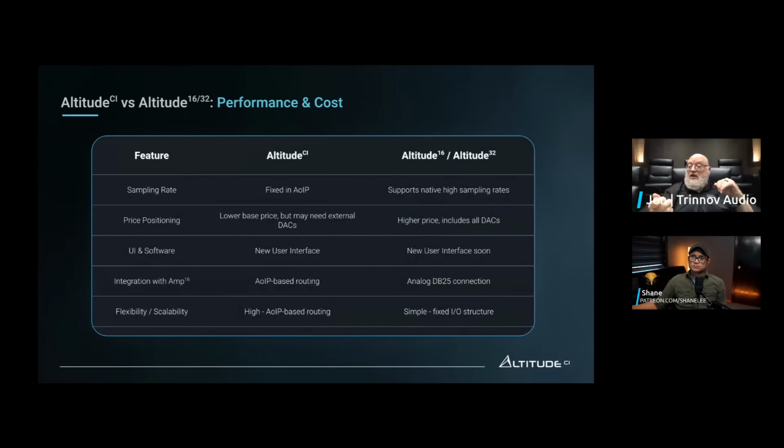And if you use the analog outputs or the AES/EBU digital, the conventional digital outputs of the CI, we will give you that 96 or 192 kilohertz result of all of our processing. But through audio over IP, it has to go down to the lowest common denominator that everything else on the system that knows how to speak Dante or AES67 understands, right?